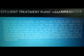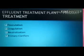Considerable attention is focused on reducing water inlet and outlet velocities to limit turbulence and promote effective settling throughout the available tank volume. Baffles are used to prevent liquid velocities at the tank entrance from extending into the tank, and overflow weirs are used to evenly distribute spill-out liquid leaving the tank over a wide area of the surface to limit resuspension of settling particles. So this is what was discussed for the preliminary treatment process methods.